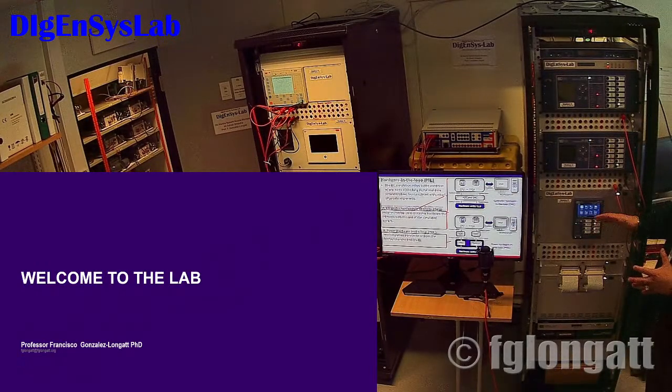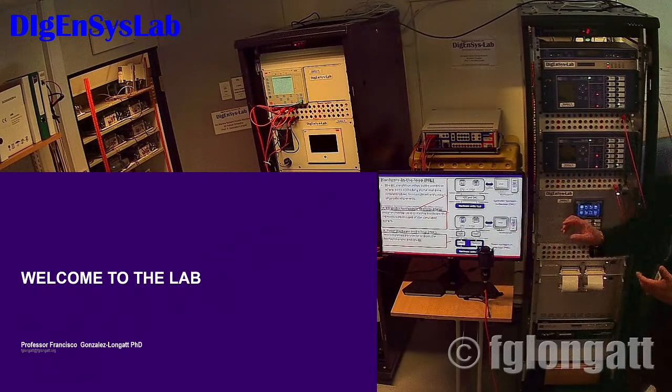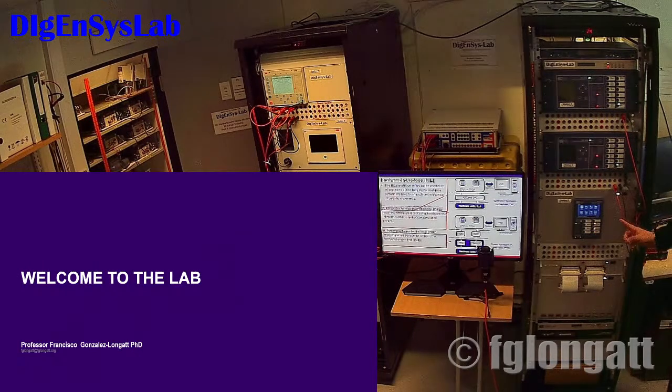But if we need to send real signals, for instance, this device is receiving 183 volts and up to 5 amps. That means that you need something strong and expensive to create those signals, okay? And that is power hardware in the loop. Power hardware in the loop is what you are doing, because we are creating the signals inside here. We are going out with very low power, then we go to the power amplifier, and from the power amplifier, we are going into the relay, okay?